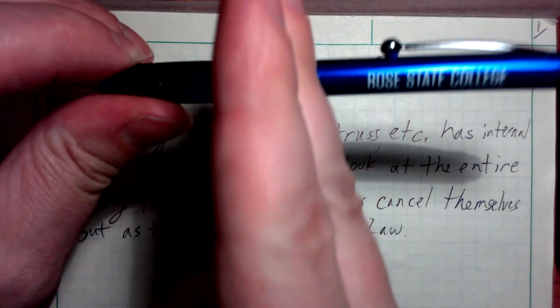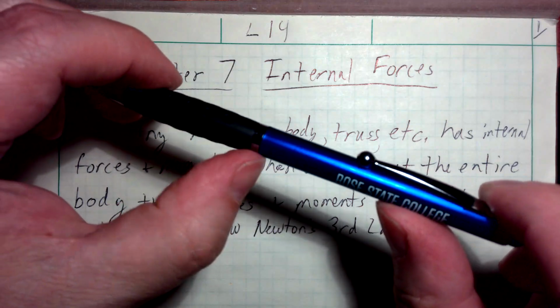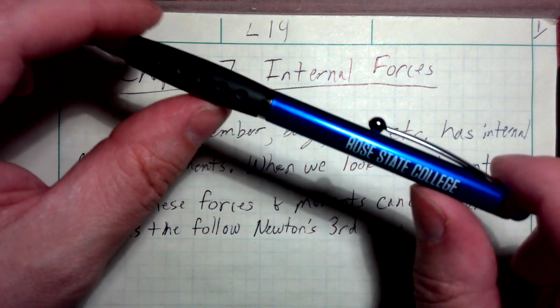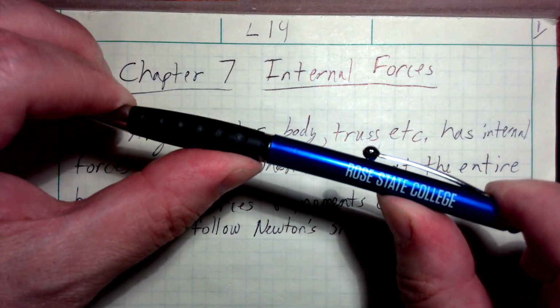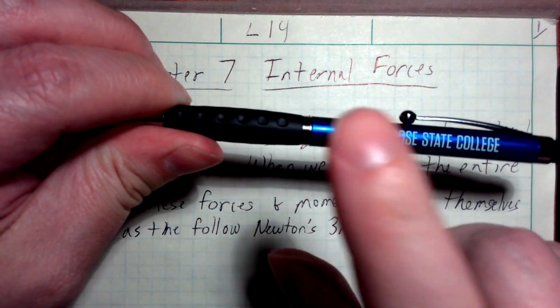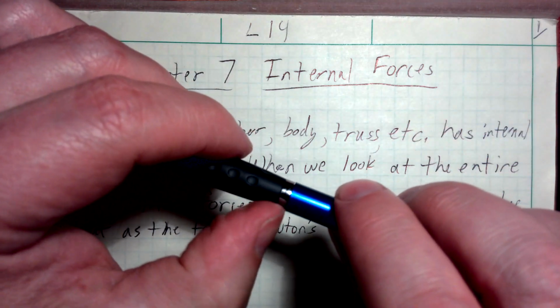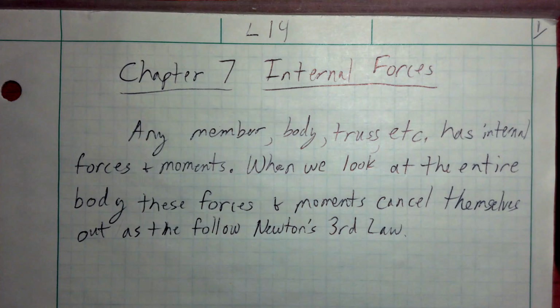And if I analyze this by cutting right there, when I've loaded this up, and I just look at, all right, tell me how much the bending moment is in there. Steve, why in the world do we want to do that? Well, if I wanted to know when this thing's going to break, I need to know when the internal bending moment exceeds the strength of the plastic threads that are holding this thing together. That's how I would analyze the failure.